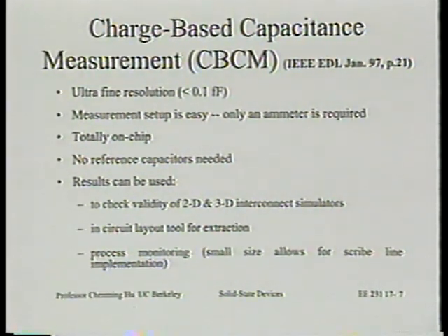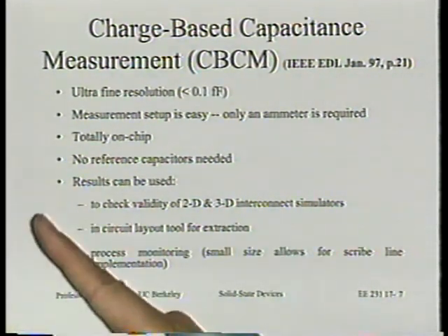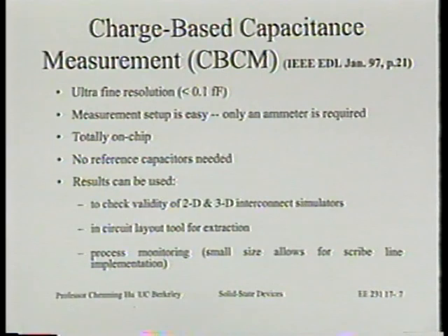So at this point, we want to talk a little bit about the clever idea to measure capacitances. How do you measure capacitance? After all, we're talking about extremely small capacitance, which probably boggles the mind. For example, take the capacitance of a minimum size metal 1 line and a minimum size metal 2 line that cross each other. What is the capacitance at this cross section?